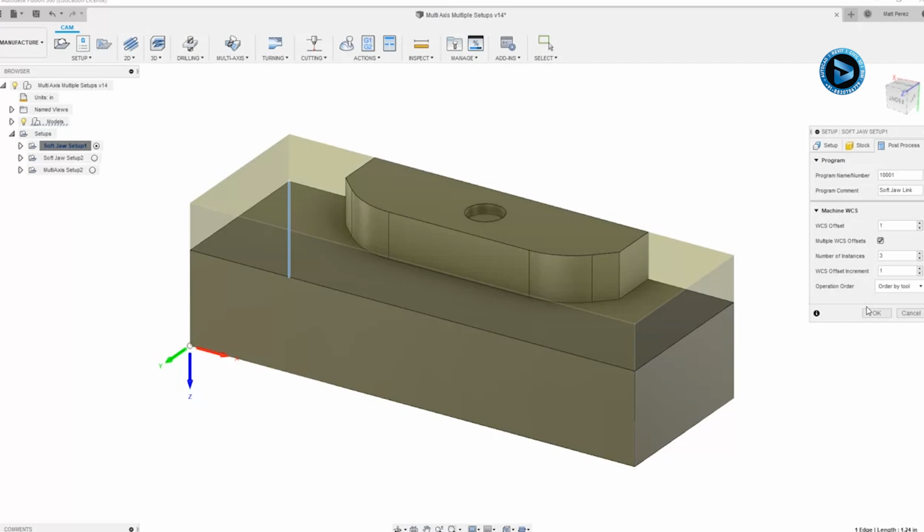Every time the tool comes up and goes through a tool change, it'll wrap it up to the home position of the machine, it'll change the tool, and then it'll come back, and each time it has to stop and start the spindle again, stop and start the coolant. There are a lot of other things that happen to make that process work.